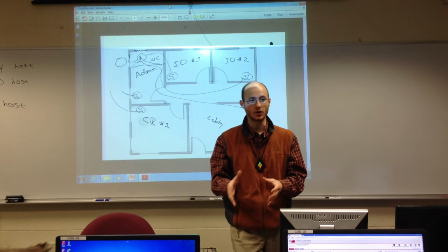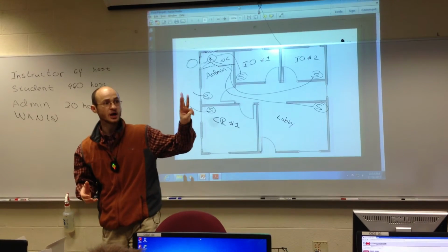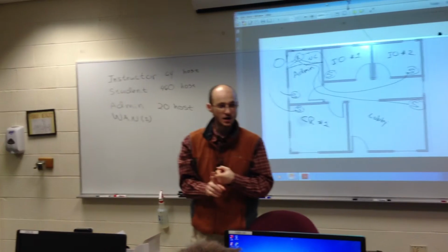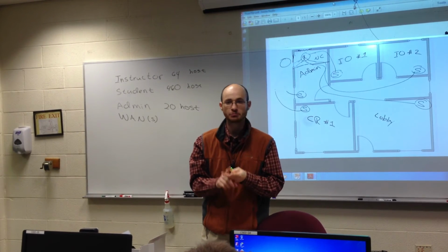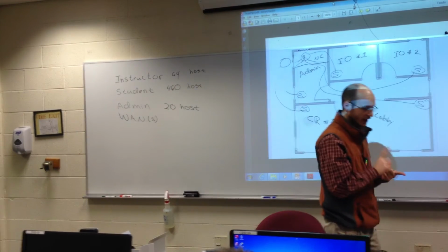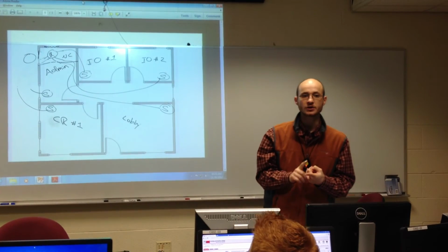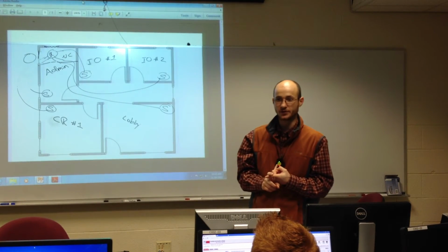This is going to be the backbone. This is going to allow you to install your vertical cables. Now there are going to be 3 terminologies that we're going to cover: horizontal, vertical, and patch cables. Make sure you understand the difference. Vertical cables are used to connect wiring closets or telecom rooms together.